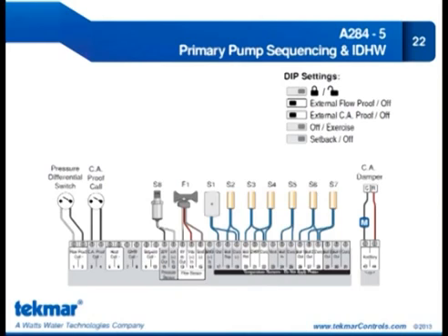So if we look at combustion air, we're going to look at the auxiliary relay, which is terminal 43, 44. That can be defined to be one of two things. One, a combustion air damper motor, or it can be used for a domestic hot water recirculation pump.